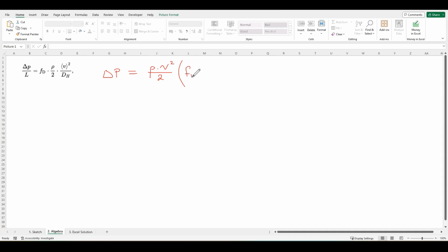So you've got your friction factor, and the two terms that sit within these brackets can be split into frictional losses in the pipe and then fittings losses, so the sum of your K values. Again, these two terms inside are dimensionless. So essentially what happens is you get a multiple of a velocity head, and you would refer to this term as your velocity head. So that's the first thing to consider.